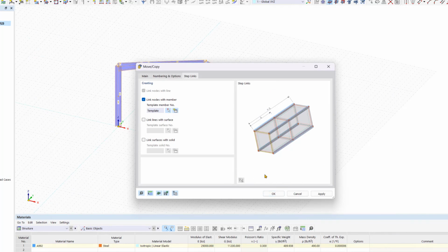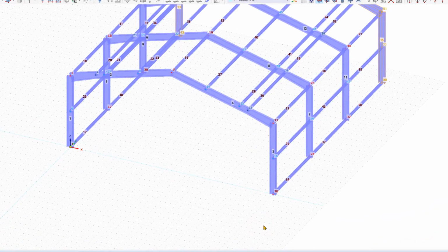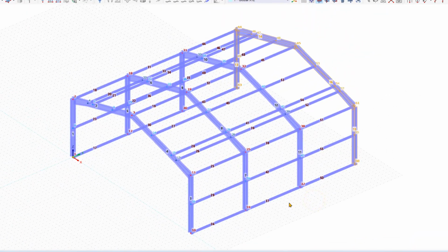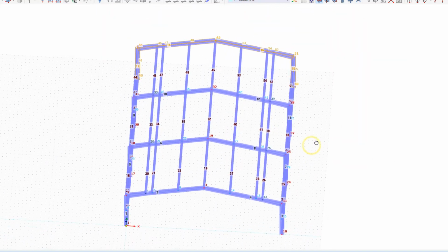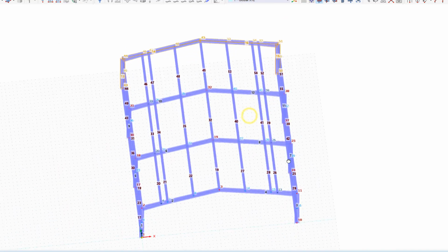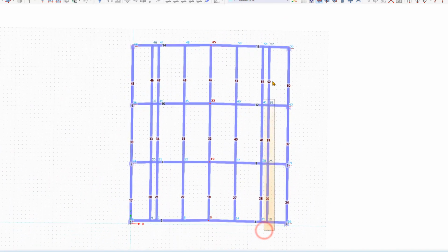The section is taken over, and a 3D hull is now created from a two-dimensional frame. The stiffening members at the start of the taper are superfluous, so we delete them. We can simply select them from left to right by holding the Control key. And then we can hit the Delete key.